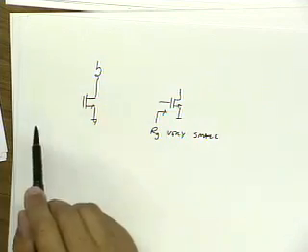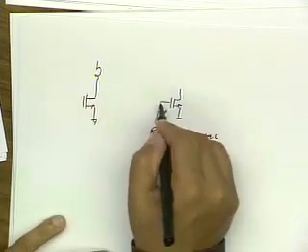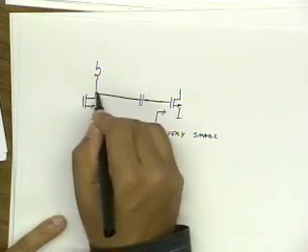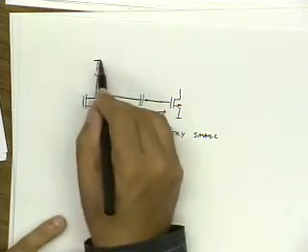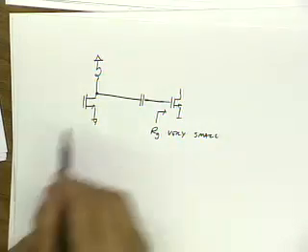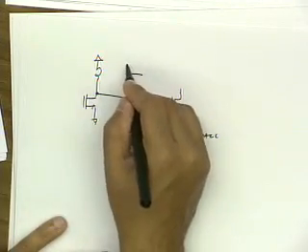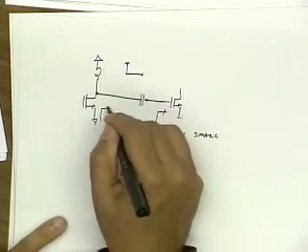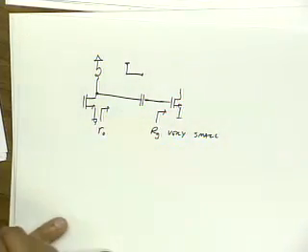So I get an impedance match between these two amplifiers. Well, to do that, I connect a capacitance in series and an inductance to ground. Right? So this is my L matching network. And now, looking out here, I should see RO for an impedance match between these two stages.